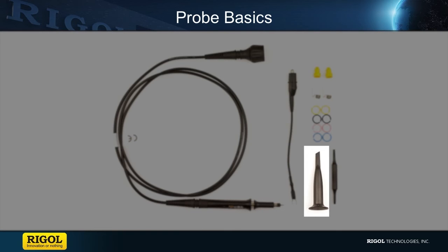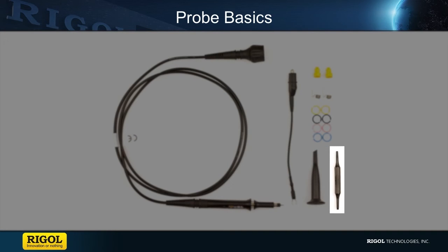Next, there is the probe hook or witch hat, which is used to connect the probe to the circuit. Then there is the adjustment tool, which is used to change the probe's compensation. The marker rings are used to color code the probe with the scope. The grounding spring is used to improve the high frequency response of the probe itself. And finally, the insulating cap is used to prevent short circuiting when probing with just the tip of the probe.